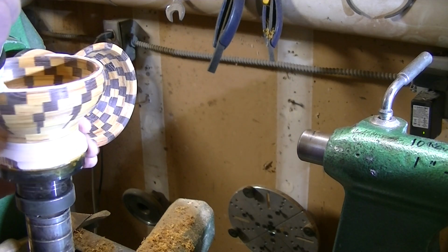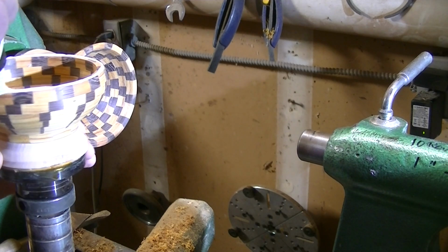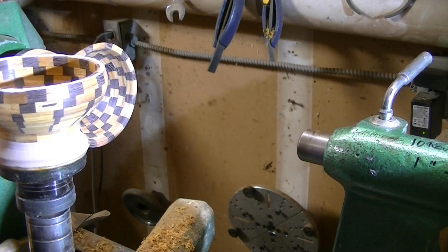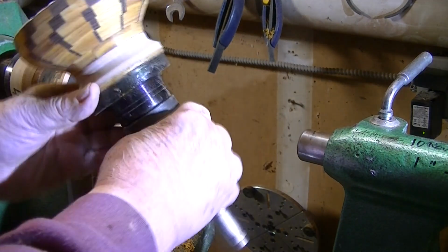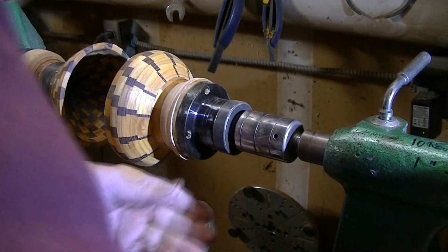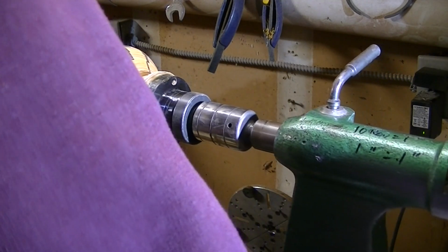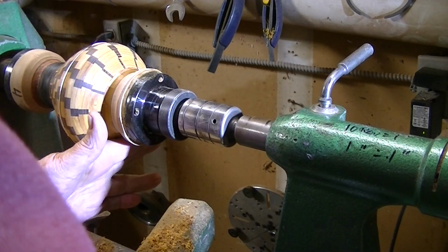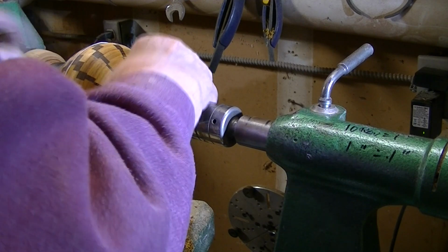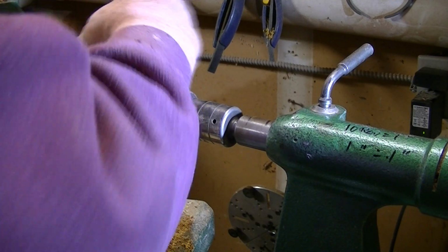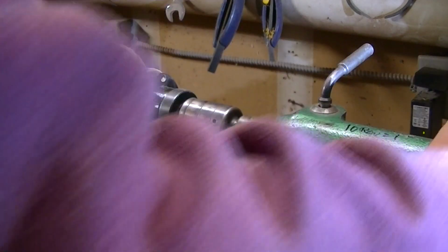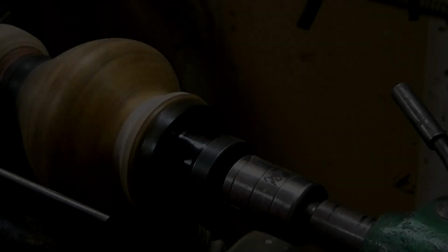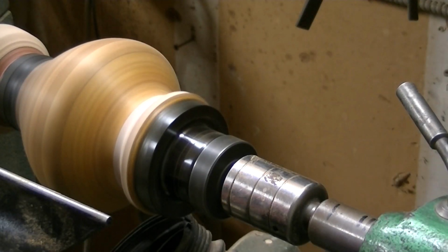Small bead of glue. If there's any seepage on the inside, that'll have to get cleaned up through the opening, a little scraping. If there's any on the outside, I will cut it away in the final cleanup. I will not try to wipe that glue away. The glue will get down into some pores and will cause the finish that goes on to be a little spotty in those points. Line them up, square it up, check my rotation, lock it down, and wait for the glue to dry.